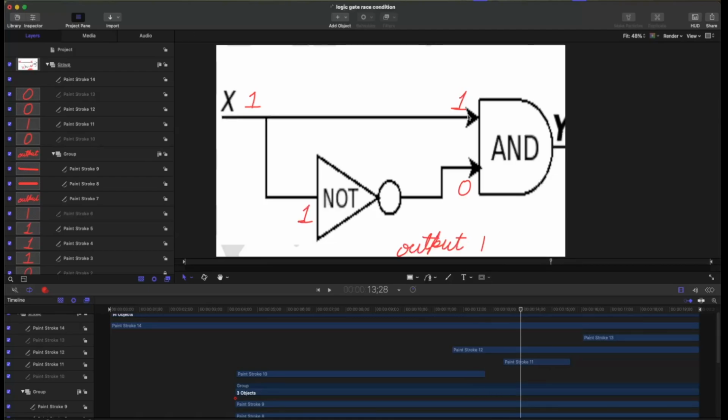Right now, see, both of the inputs are 1 and 0. For this, if there was no delay, the output would have become 0. But as there is propagation delay, hence AND is going to become 1 here. And it is going to stay 1 for a small amount of time. Then it is going to become 0 again, right? This is what is actually happening over there. I hope that this actually gave you a better visualization on the topic. Obviously, drawing with your own hand is the best way, but this will help you understand it even better.